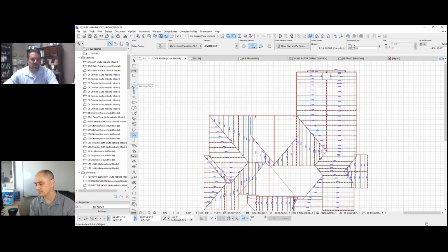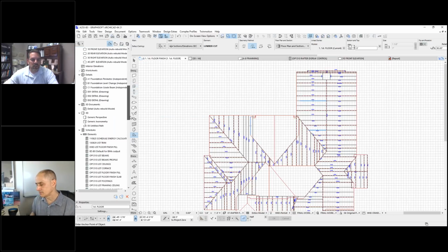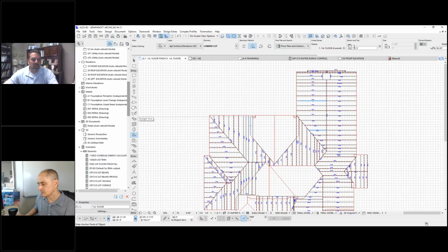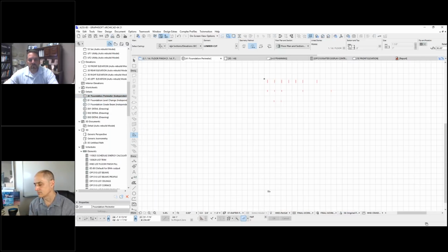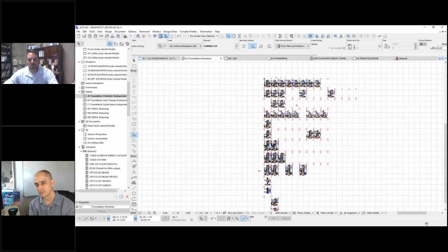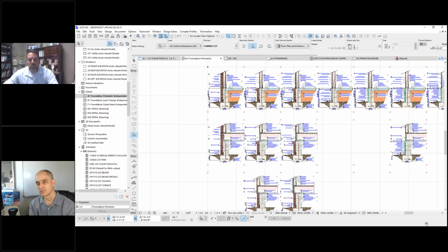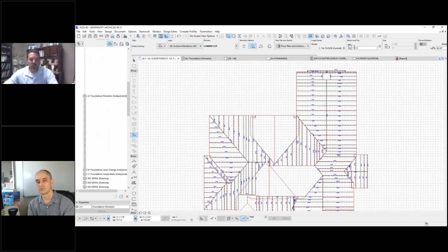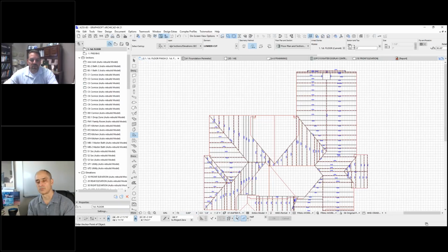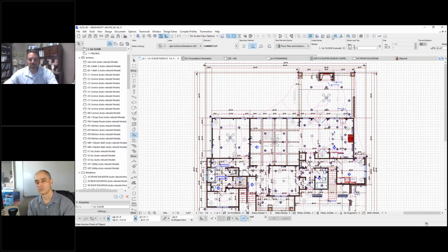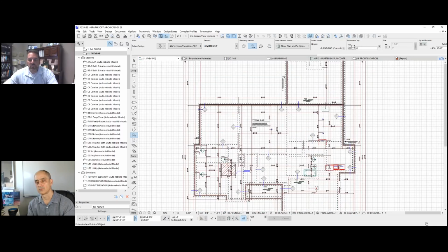Yeah, foundation details we use as external Hotlink drawings, where we have a lot of our case scenarios. And then when we insert this on our sheets, all we do is reduce our sheet down to which detail we want. So that's an unlinking one. But then in the foundation plan, we have a symbol that we insert that will reference that detail.